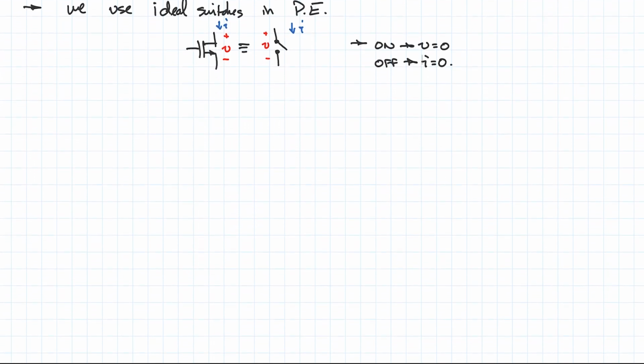Now, when analyzing these circuits, they're usually switch mode circuits. That means they have two or more operating states based on the conduction states of the switches. That doesn't mean you have to analyze every single state, because in most cases the switches operate in pairs, and if they don't, they're periodic. So you only have to analyze it for a single period, and then after that you can just repeat the same behavior, because the behavior is the same throughout periods, hence the nature of being periodic.